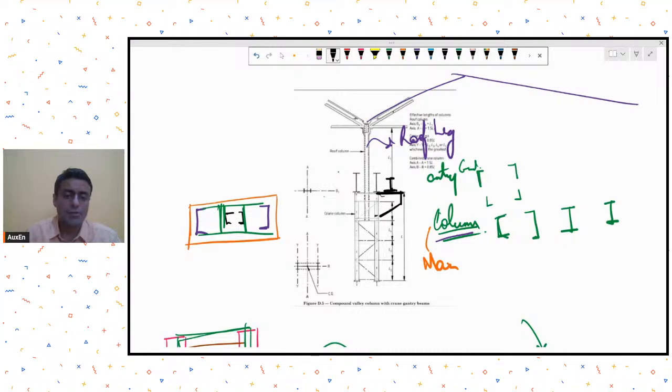There are other options where you can hang the gantry girder from top. The crane will not be running over the gantry girder, but it will also be hanging. Sorry, you can hang the gantry girder from the top, and there have been such projects where the crane bracket then hangs like this from the bottom flange of this gantry girder.